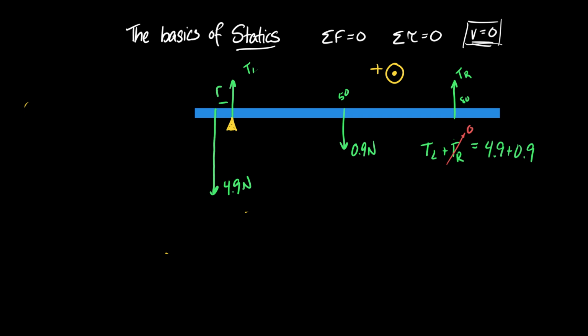So if I do all those things, I'm going to leave my pivot point where it was. I'm identifying the possibility of 3 torques. The torque from the 500 gram mass, the torque from the meter stick, and the torque from the right-hand cable. I've laid all my torques out. I want them to sum to be equal to 0.